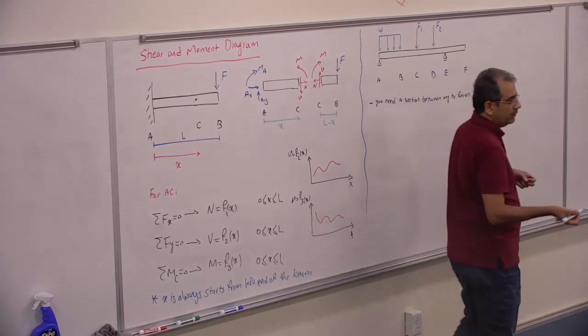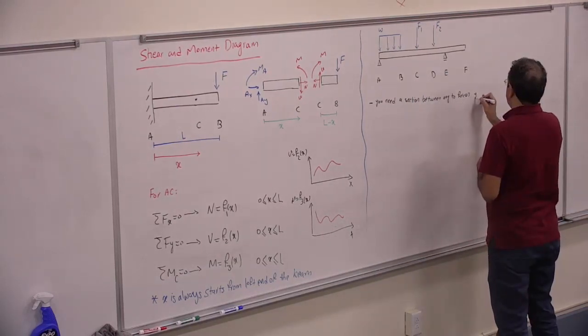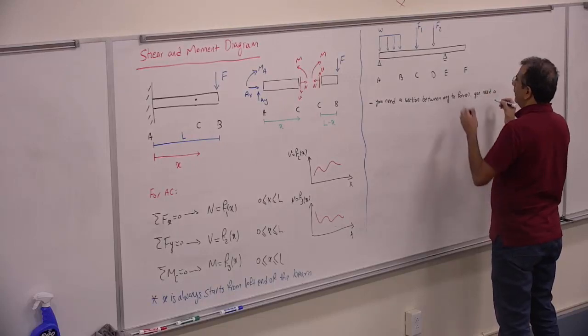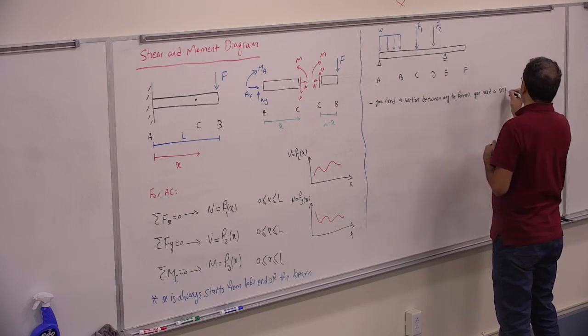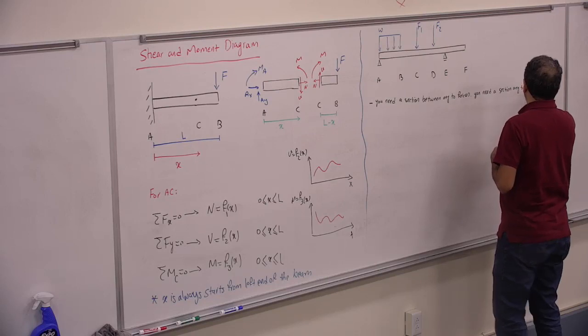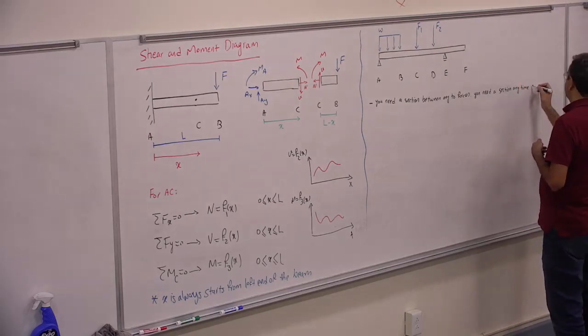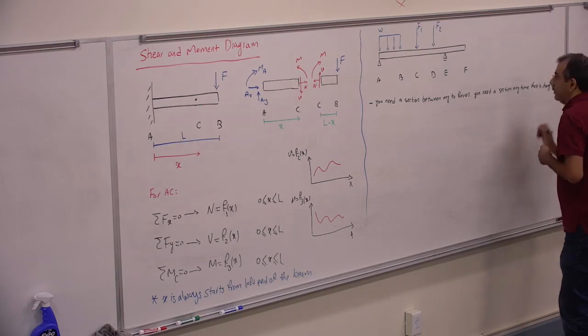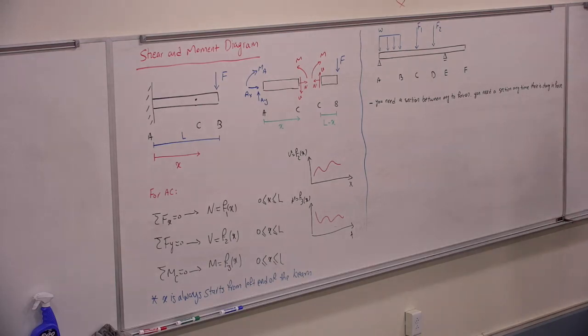In other words, you need a section anytime there's a change in force. So anytime I have an external force change, I need a section.